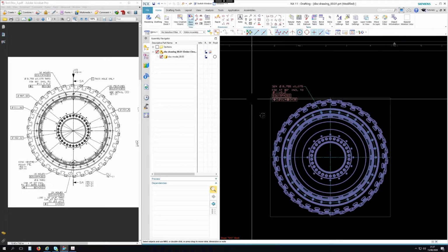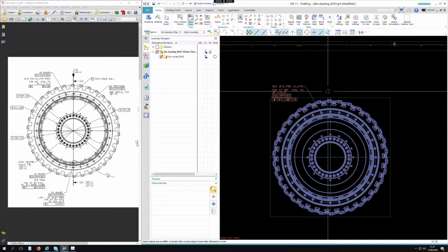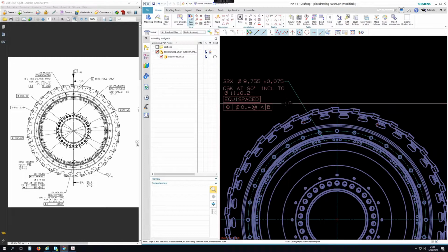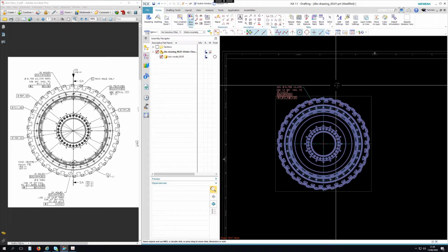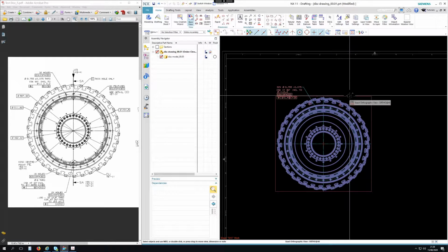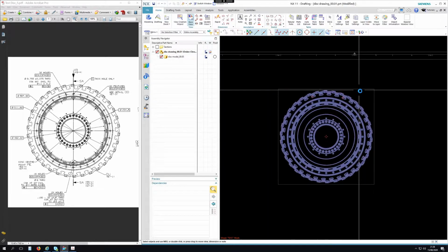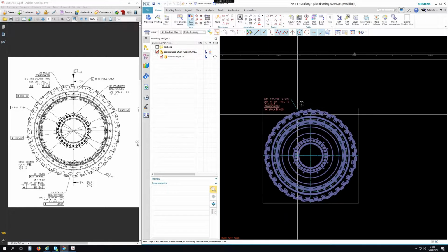One thing you must try and do when you're doing drawings, you need to make sure that this text and anything you put on the view goes with the drawing border. That way you can move the drawing borders and things around slightly later on to tidy it all up. So always double check now and again by moving the drawing border that the information goes with it. You don't want it to be left behind somewhere.